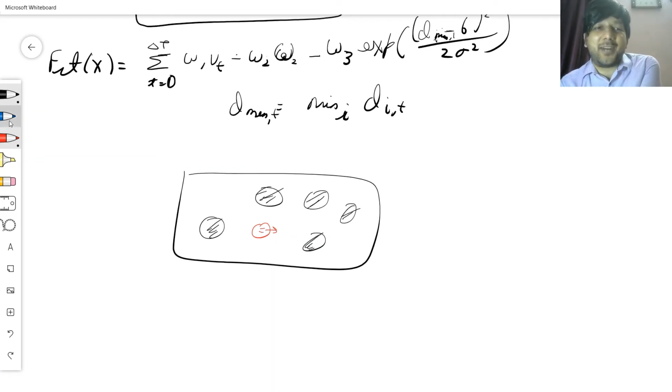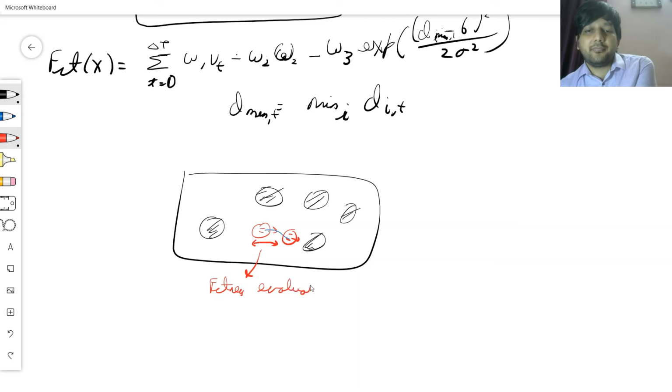I load the first one for, let's say, 3 seconds, and it goes over here. It'll get a good fitness function value because linear speed is maximum, angular speed is minimum, and the distance from obstacles was anyway large. So that's the fitness evaluation of the first individual. Now the problem is with the second. What happens is I load the second individual to calculate its fitness function value.